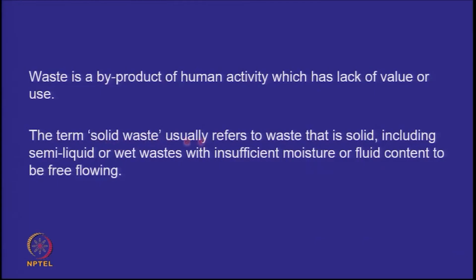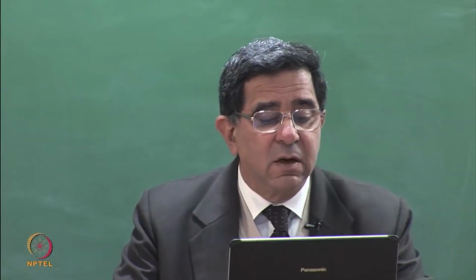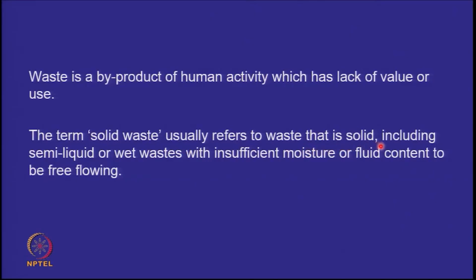And the term solid waste refers to waste that will not move away from the site where it is deposited, because this question will come to you always: is slurry waste solid waste? Is wet waste solid waste? So the term solid waste refers to waste that is solid, including semi-liquid or wet wastes with insufficient moisture or fluid content to be free flowing. So wastes which can flow by themselves don't come under the terminology of solid waste. So we are dealing with all waste which will stay where it was generated or in a nearby area and does not flow away to the nearest drain or river.